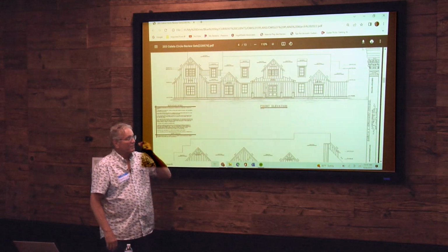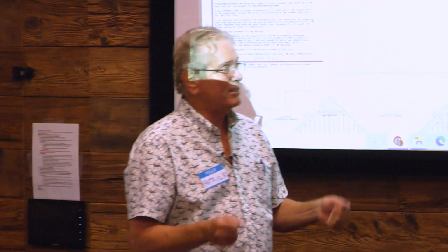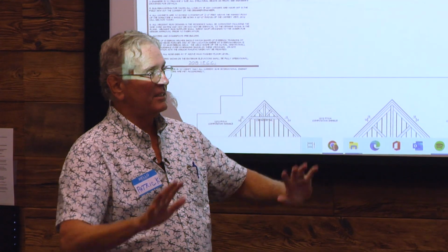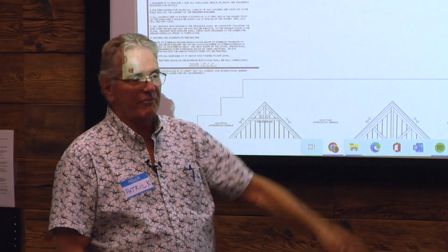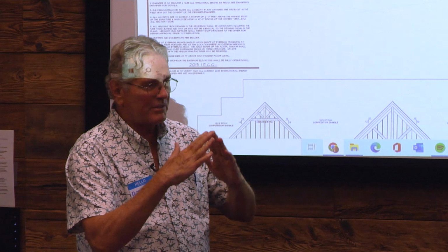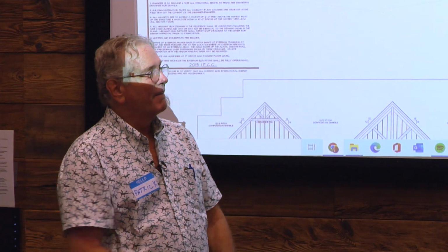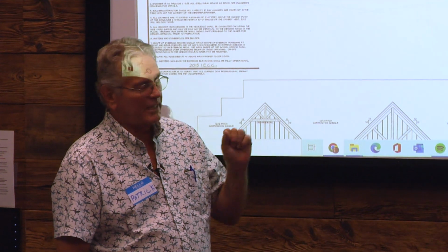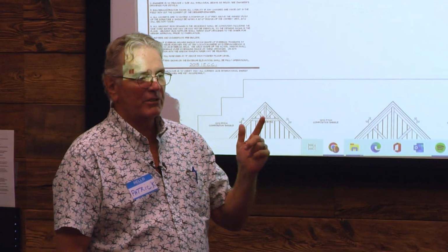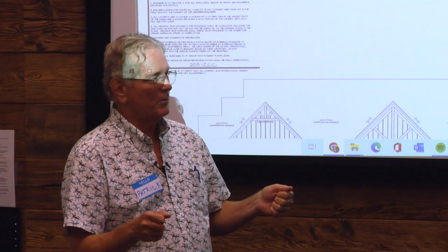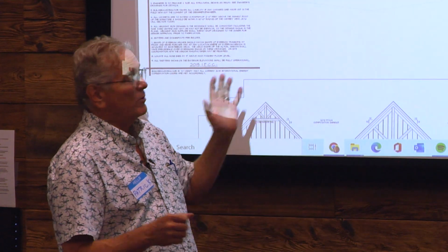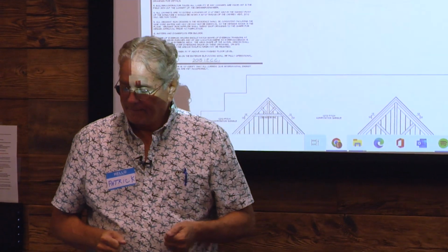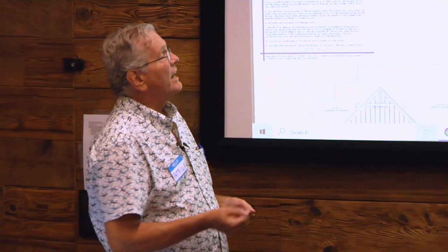Again, this is the thing that I look at consistently while the framer's working. If the house going up in a skeleton structure looks like this, I feel comfortable that he's put all the pieces together the way it's supposed to be. If there was something done out of place, I can almost guarantee it would show up at this stage when the owner steps back in the street and looks at the plans. So when I go to jobs, I'm always looking at the plans and making sure they conform to what I see on the elevation. If it doesn't, then you just find out why.